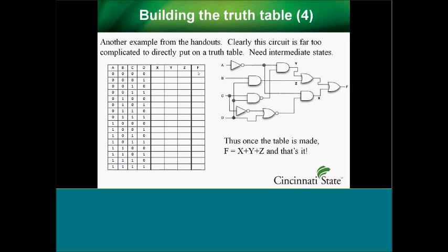One of the keys of teaching this course is really trying to figure out where the students are having their problems. Right after a student writes this AND gate, you'll see a student write down something like B or C. I'm like, wow, okay. Well, the first thing is it's not an OR gate, and second, they didn't see that it's D coming up. So they're not following the wires in the schematic very well, and I'll see that a lot. For this one, for instance, they may not get that this is a NAND gate, or they'll write C or D, all prime, like it's a NOR gate. And okay, well then I'll tell them you need to go back and study your gates.